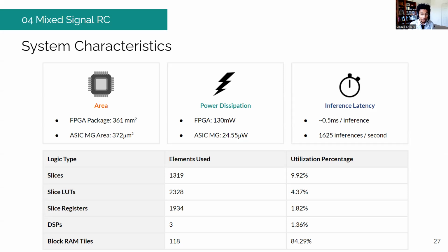So this was collected from Xilinx Vivado's tool. And the activation function, which would be expected to consume a lot more power, had even lower power consumption, right? So that was after we sent the data to the ADC, told the ASIC to actually perform that transformation and then read it back. And that's the estimated power dissipation for that as well.